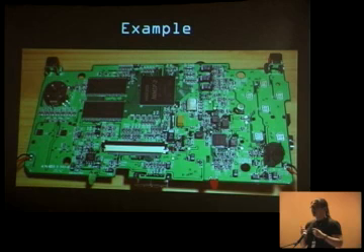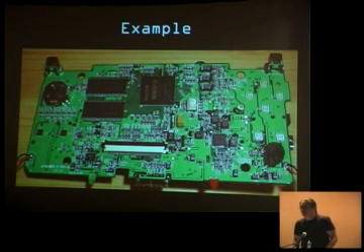It comes through the power supply, through the outside buses, out-of-band things, backdoor ports, JTAG ports, all these kinds of things. Because the manufacturers themselves can't build a completely secure system: if they have any defect, that defect's a loss to the line. They're running at like 99% yield, and they rely on being able to rework 10% of them to get there. All of a sudden they lose 10% of their margin if they use security. There's no way they're going to give that up, right? So those things are always left behind, and usually you can jiggle them a bit and get what you need out of it enough to move things forward. We'll see. I could be wrong.